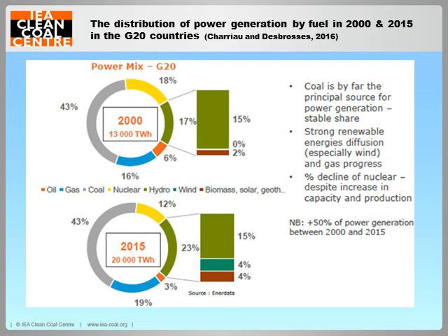Now, the increasing use of renewable energy is already impacting the cost and utilization of coal power generation. But I must point out here that unlike the dispatchable sources of electricity, such as coal-fired power plants, non-dispatchable technologies such as wind and solar power provide a variable output to the grid that is not sufficiently reliable energy to be considered as capacity. Currently, renewables cannot be relied upon to meet the peak energy demand, under certain weather conditions, of course. For example, no sun or no wind. On top of all that,